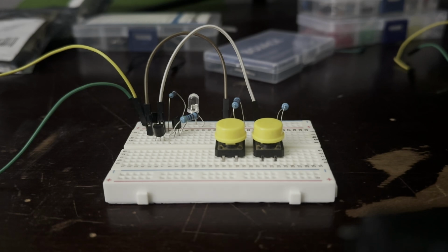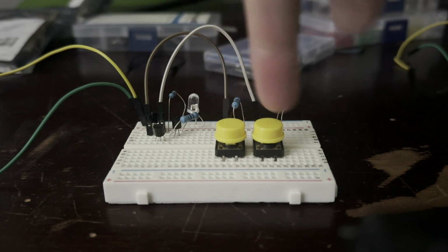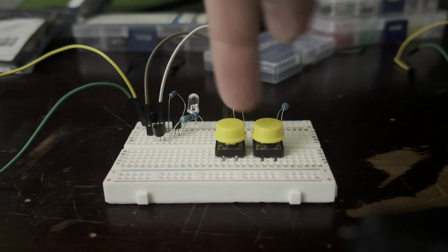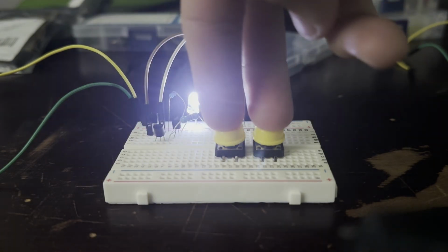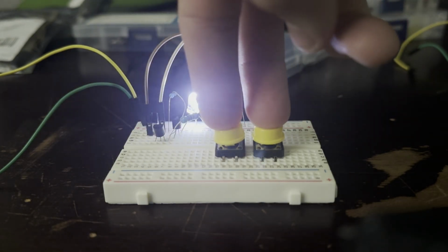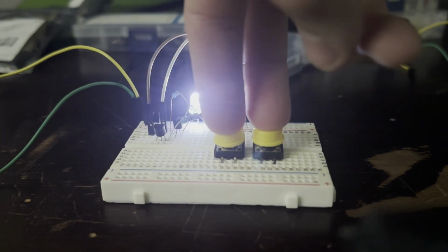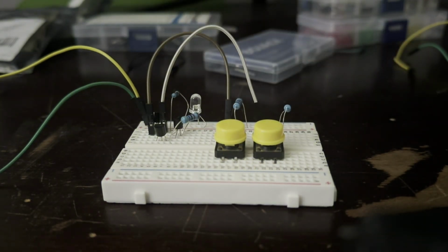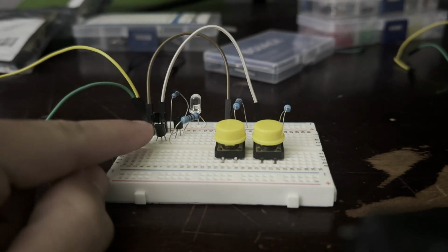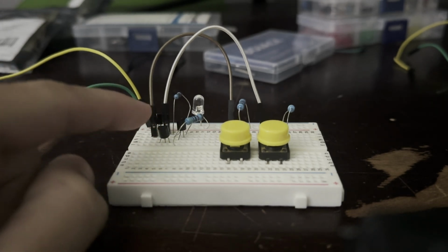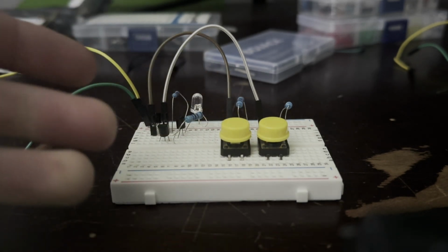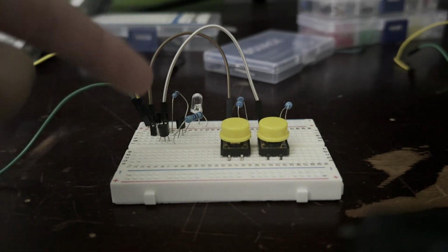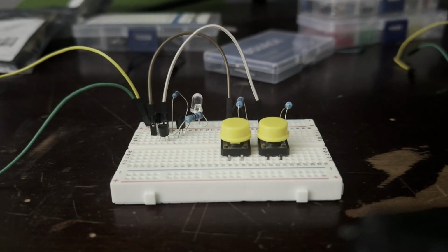So this is a little demonstration I made of an AND gate. As you can see, both the inputs are off, the output is off. I can press either one on, and when I press them both, the output becomes on. And it works using these little transistors right here. So the inputs are connected to these 2 resistors to limit the amount of electricity going into these little low power transistors.